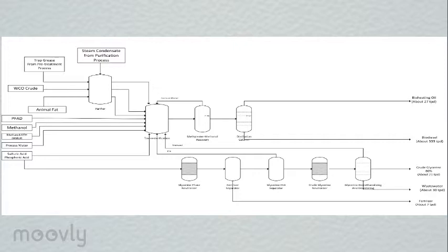In the fertilizer separator and glycerin fast separator, the generated potassium sulfate is discharged via a screw conveyor to a container as pasty fertilizer. Meanwhile, in the crude glycerin neutralizer, the acidic glycerin phase from the tricanter is neutralized with the basic catalyst in the neutralization tank, and the generated potassium sulfate is filtered off and discharged back to the acidification tank.